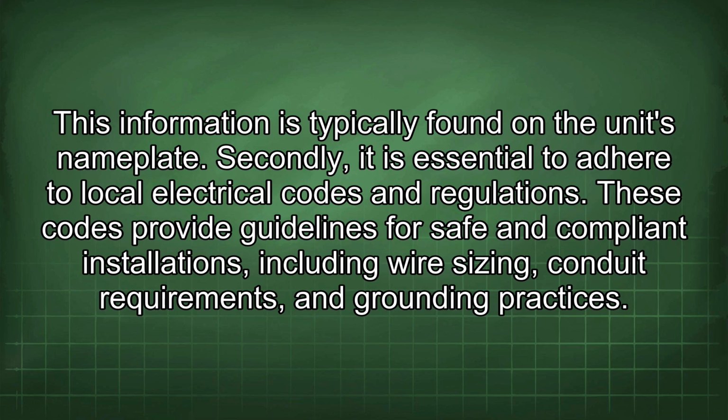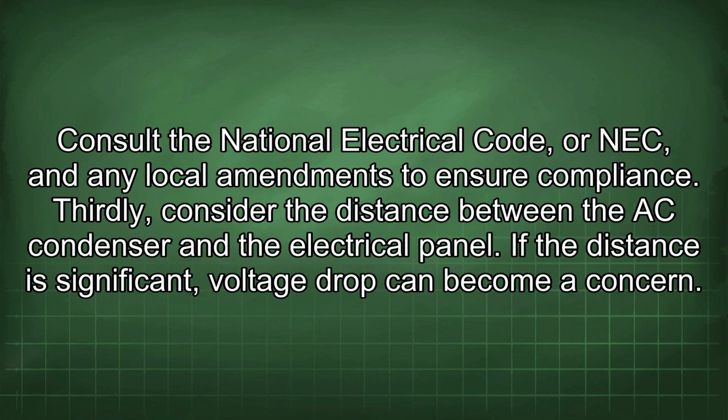Secondly, it is essential to adhere to local electrical codes and regulations. These codes provide guidelines for safe and compliant installations, including wire sizing, conduit requirements, and grounding practices. Consult the National Electrical Code, or NEC, and any local amendments to ensure compliance.